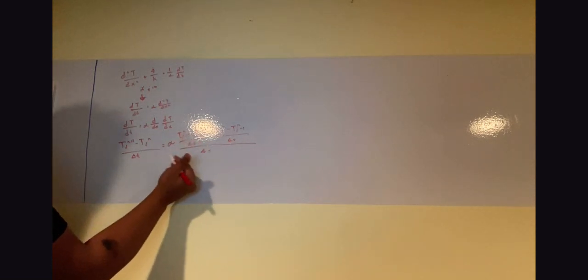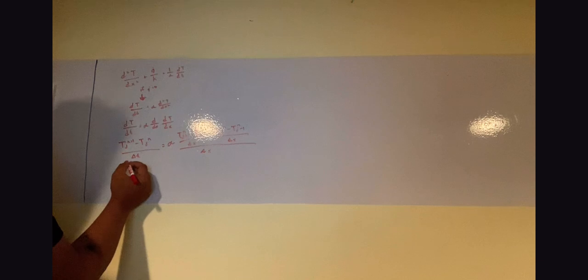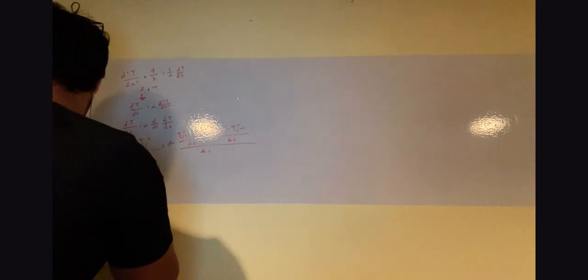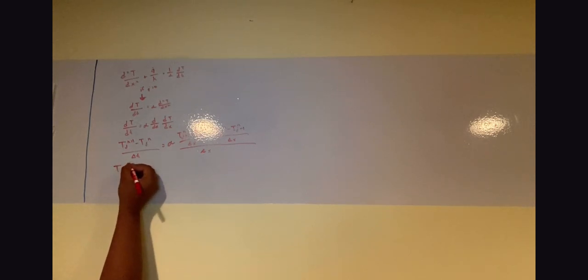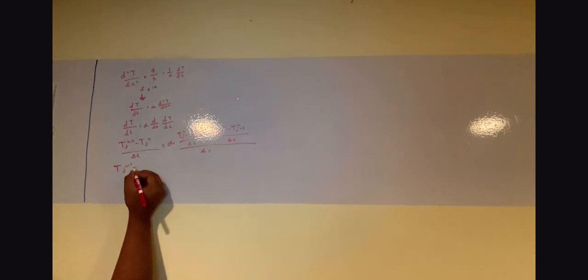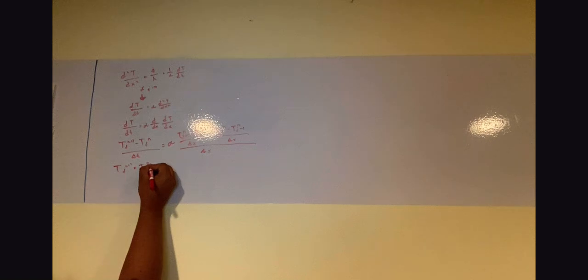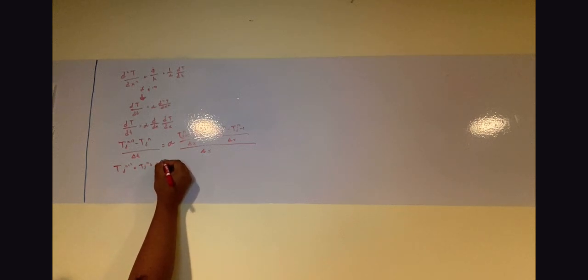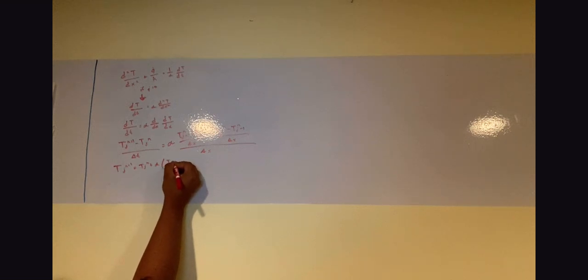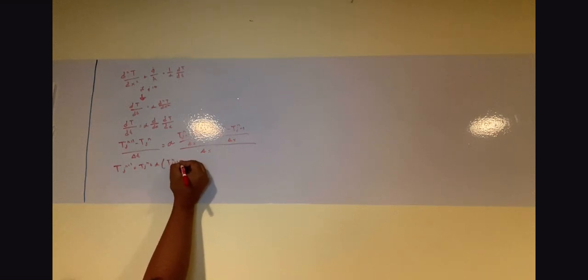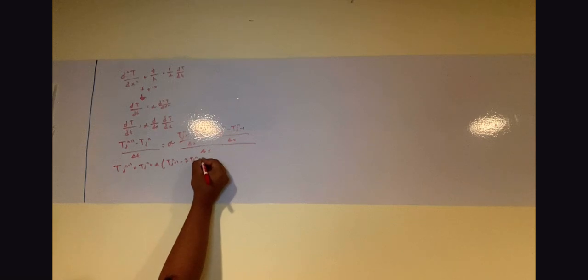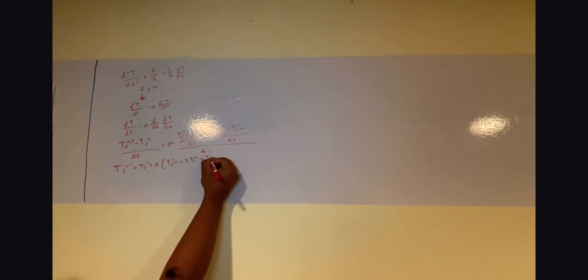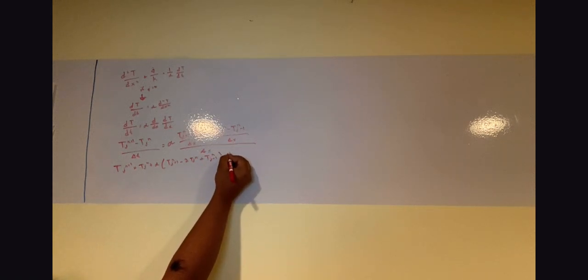And so if we clean this equation up a bit and we move the change in t over a little bit, we will get Tj n plus 1 is equal to Tj n plus alpha multiplied by Tj plus 1 n minus 2 Tj n plus Tj minus 1 n all multiplied by change in t.